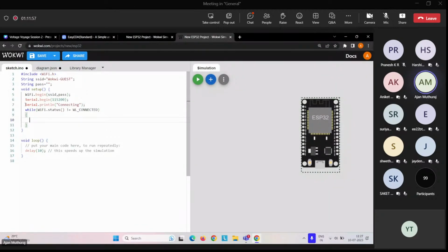And do remember that Serial.print is not actually important for connecting; it only displays stuff. It helps us in identifying what the board is doing, and doesn't change anything the ESP32 does with connecting to Wi-Fi. We are connecting to Wi-Fi, right? So writing connecting here doesn't make it connect to Wi-Fi automatically.